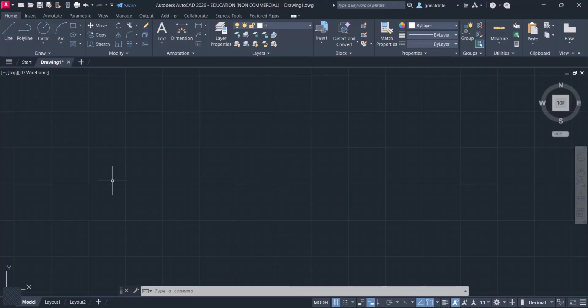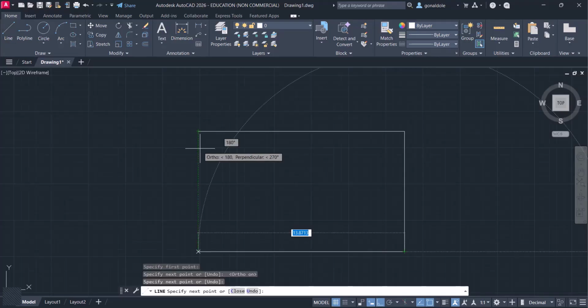So I'm just going to draw a simple rectangle. I'm going to click on line. I need straight lines, so I'll pick up my auto mode so I don't stress myself trying to get straight lines. I don't know where this line is going to end, so for me to be sure that I am on the right point, I'm going to move my crosshair to touch here first, snap to this point, then come down a little bit. It shows me the green extension that I am at the same distance as the top line. Then I left click, and left click here to close my rectangle.